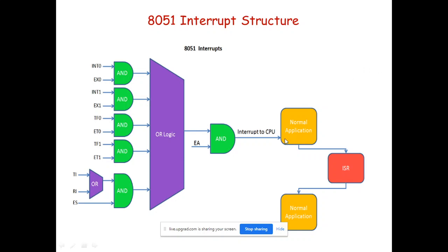Now, in the same fashion, our controller is interrupted at location 2000. That time the 2000 address is held on a stack. Then the controller jumps to the interrupt vector table. The interrupt vector table holds the starting address of the ISR. Each interrupt source has a different ISR, or different location, or different starting address of ISR. As per the interrupt vector table, the respective starting address is received by the controller, and then it executes the interrupt service routine to serve that interrupt.